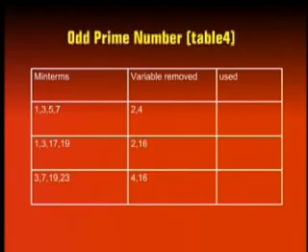Similarly, terms 1, 3, 17 and 19 form a single term eliminating variables A and D, forming the product term B bar, C bar, E. Both these terms are marked as used in table 3. Product terms in table 4 are compared to eliminate common variables. No more comparisons of terms and elimination of variables takes place. Thus, the prime implicants have been found.